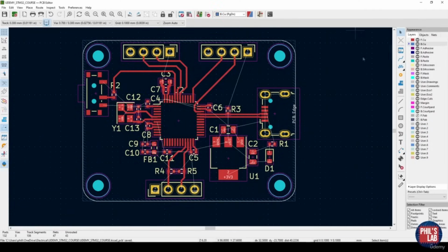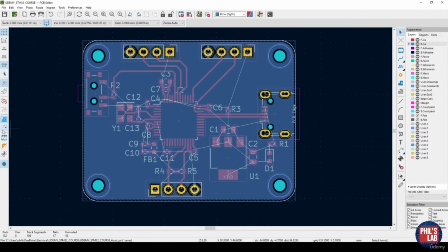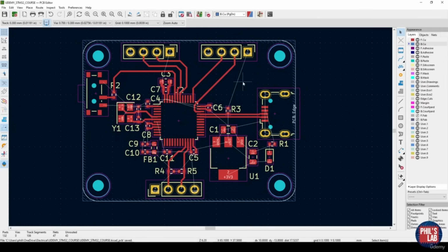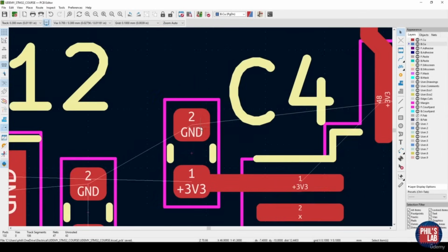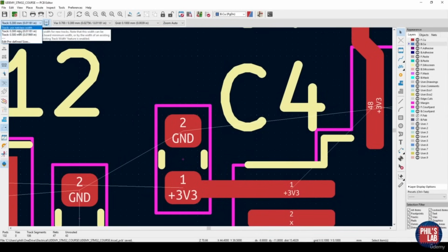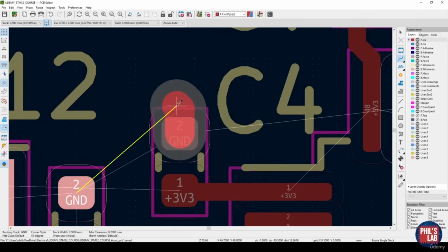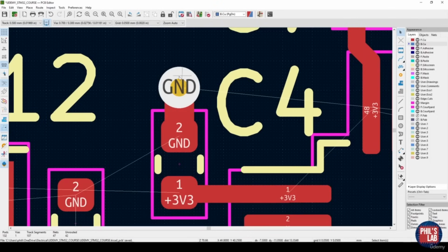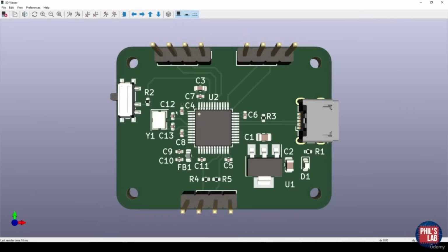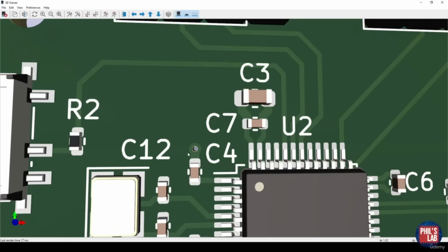And remember, because we have this large ground plane on the bottom layer, connecting up ground is actually really easy on this 2-layer board. All we have to do is, for example, if we have a ground pad, such as one over here, take a very wide trace, that is a 0.5mm trace, on the front layer, use the track tool, clicking X, routing out a tiny bit, and pressing V to then dig down. We don't want to bring the via too close to the pad because that will give problems with the via sucking in solder, so I have soldering problems. So something like this distance, fairly short, is pretty good. Again, we can look at that in 3D and see this seems fair enough.